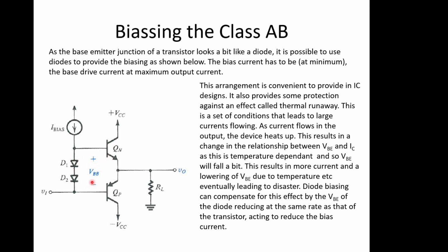exactly the same characteristics. Also helps us with a bit of stability with temperature, because the VBE across here varies with temperature, but the VBE of this also varies with temperature, and if it's made effectively from a transistor, then they will vary the same, and we will end up with some compensation for changes in VBE, which will affect the current output. So that's all good.